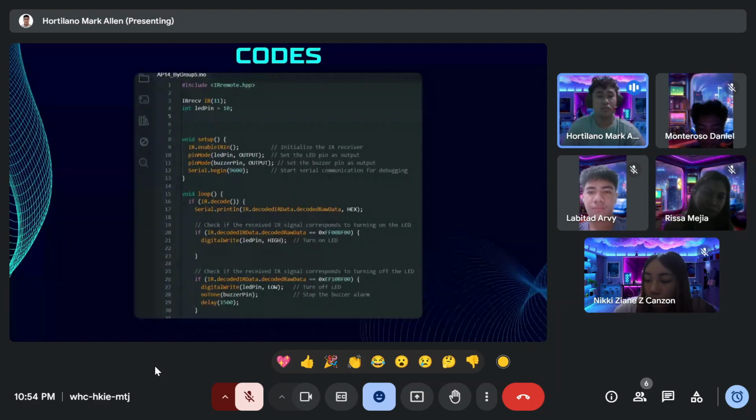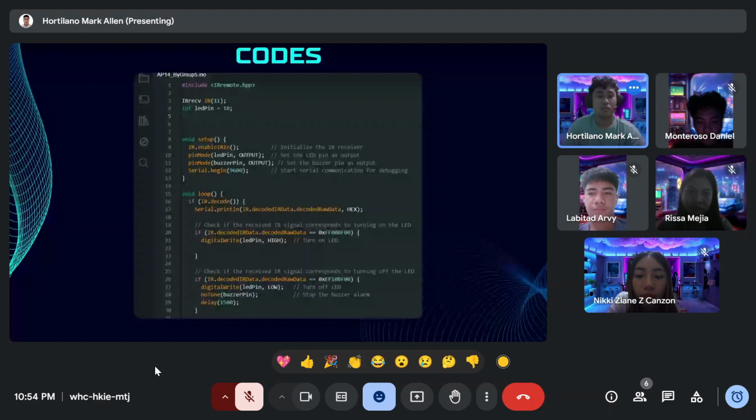Number representation array: int number[10][8], a 2D array that defines the representation of numbers 0 to 9 on digital pins 2 to 9, where each inner array represents the state, high or low, of each pin for that number. Function to display number: declare void numberShow(int i), a function that takes integer i as an input and sets digital pins 2 to 9 according to the corresponding binary representation of the number i in the number array.